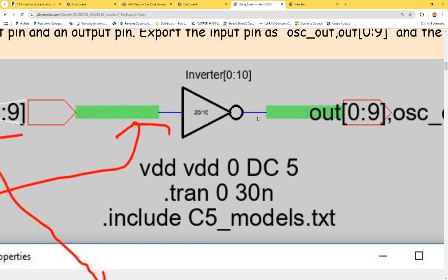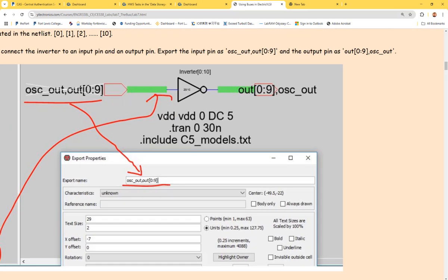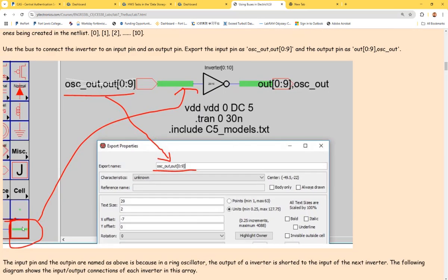If you want to create a bus, you can imagine that you are actually splitting that wire into 11 wires. So we want to use a tool in the library, which is over here, the green wire, a thicker wire, and you connect that thicker wire here. I think you just left click and right click to extend it, and eventually add a port at the other end of the thick wire, and then when you name it, that's where you can define the connections.